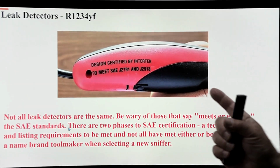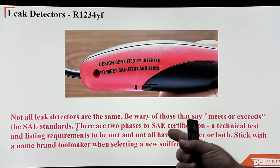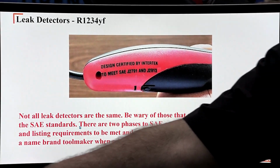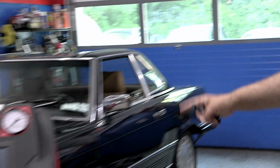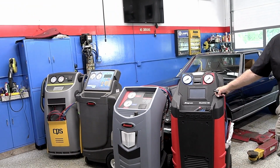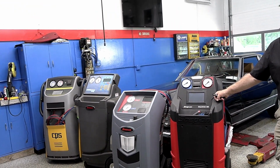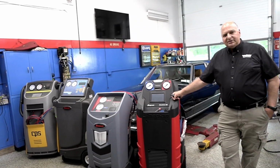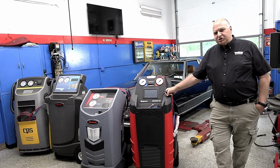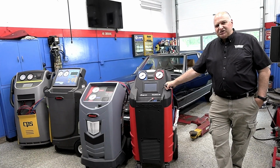We still utilize this, but when you are using this machine on 1234yf, right, this or the CPS, these are the 1234yf machines. When you're using it, it's going to go through a mandatory 10-minute vacuum hold. Then it's going to put 15% of a charge in the AC system.